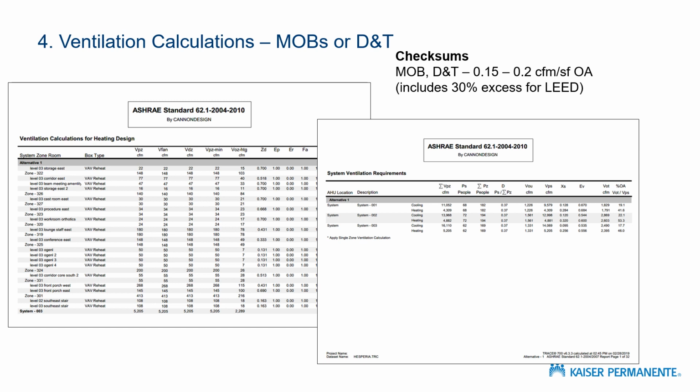So that's acceptance criteria, which brings us to the long part of the discussion that we're going to have that has to do with ventilation calculations. The ventilation calculations in healthcare buildings are really the keystone of the whole system design performance. So to get the easiest stuff out of the way, when we do our medical office buildings or outpatient clinical buildings, we do not follow ASHRAE Standard 170 or California Table 4A.